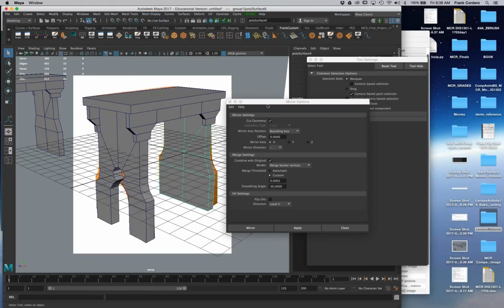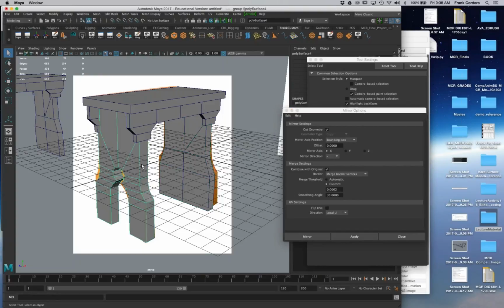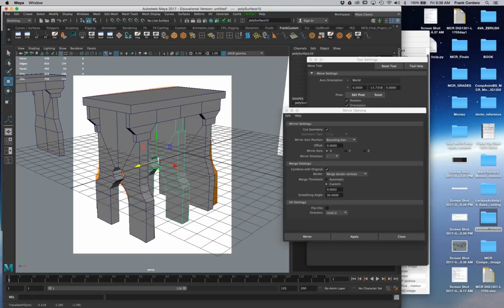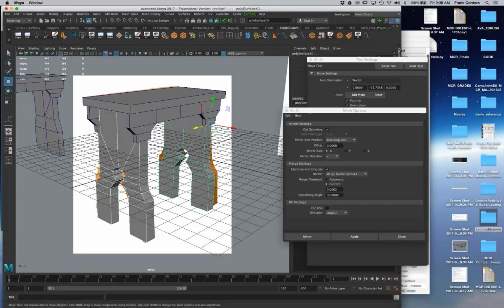And now I've got something in its place. So now I'm going to go ahead and command duplicate. And then I'll just change the pivot, D middle mouse button, D middle mouse button there. And then I'll just snap it to that position. All right. So this guy can go away now. So now we have a little bit more of an advanced block out for this part of the model.